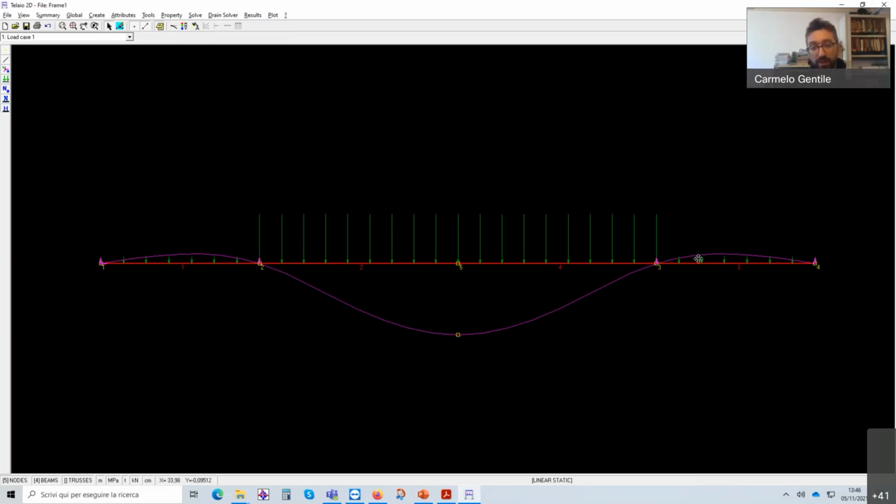We have our concavity: here we have positive bending moment, and here we will have negative bending moment. We already know that, because we have already discussed it. So negative bending moment from here to almost here, and from here to almost here.